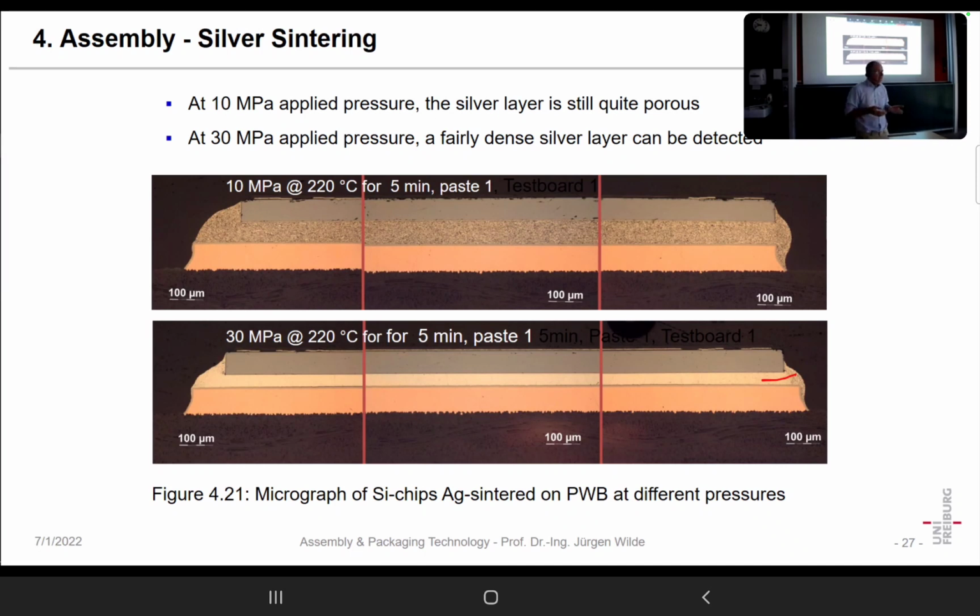But unfortunately, we cannot make the solder much thinner, because the thinner the solder is, the faster fatigue will be. In that case, shear strain in the solder is higher, because shear strain is always displacement divided by thickness. So making it thinner just increases shear strain naturally.